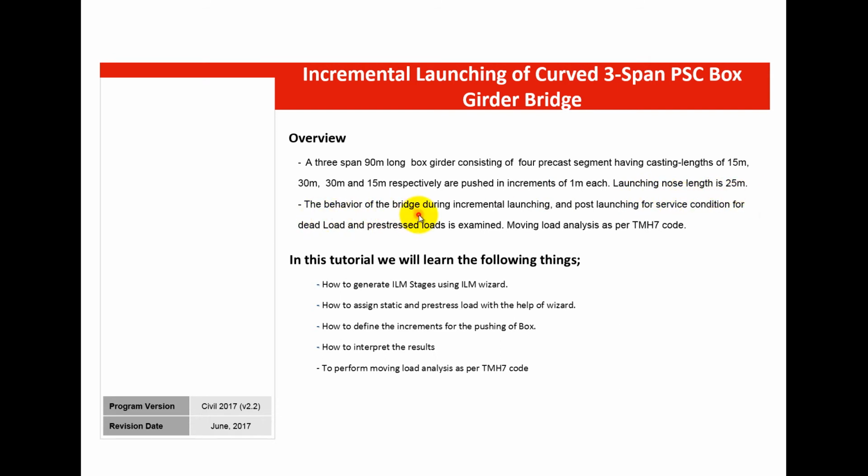The behavior of the bridge during incremental launching and post-launching for service condition for dead load and pre-stress loads would be examined. And then we'll perform the moving load analysis as per TMH7 code. So in this tutorial you learn the following things. First, how to generate the ILM stages using the ILM Wizard.